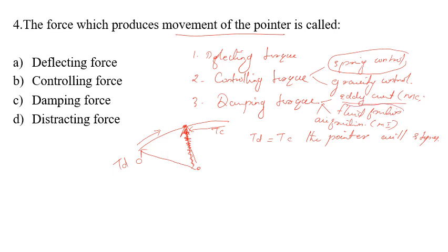Due to the presence of fluids in the measuring instruments, if there are any leakage issues, the entire machine gets damaged. Because of the leakage issues, we are not providing fluid friction damping, though there is a method to provide damping force by fluid friction. Due to these limitations, we are not providing fluid friction nowadays.